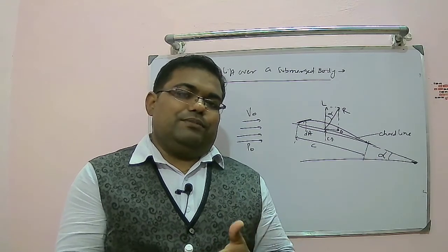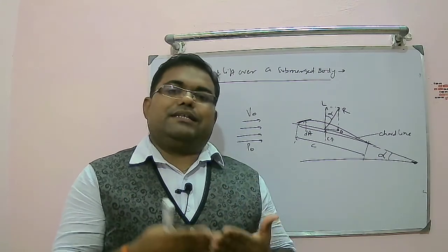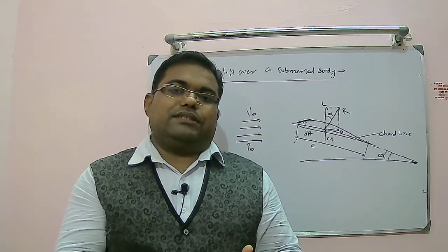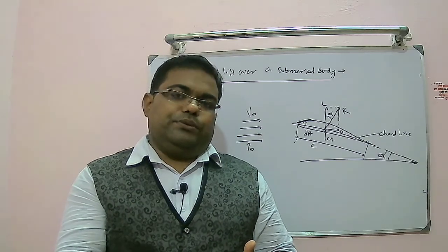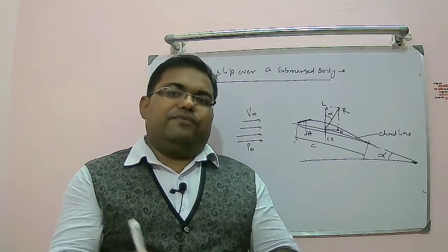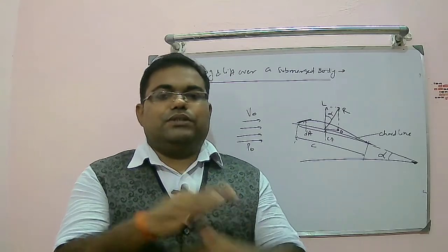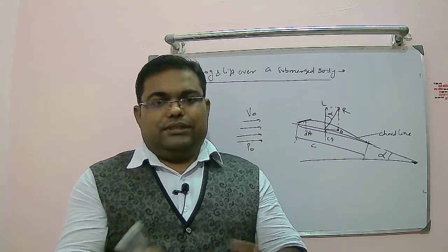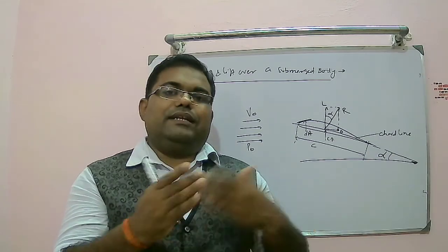Why does shear stress come into the picture? Because the fluid domain has viscosity, and viscosity will resist its motion, and viscosity will contribute to the shear stress. So the aerodynamic force is the combined effect of these two forces, pressure forces and shear forces. So as a result, you will get the aerodynamic forces.